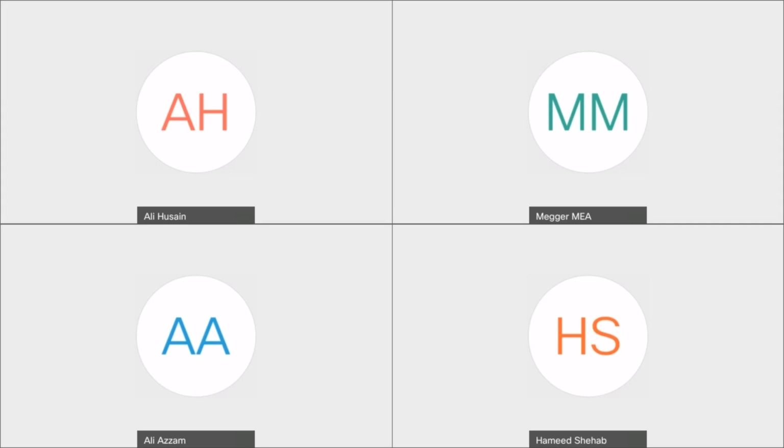Follow the circuit breaker manufacturer recommendation. If the above is missing, you should choose a point in which the motion of the movable contact, as close as possible, is reflected.